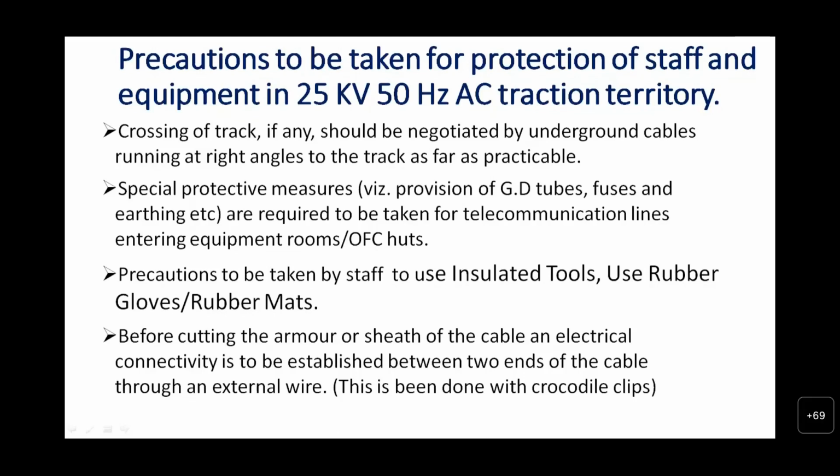Precautions to be taken by staff: use insulated tools, rubber gloves and rubber mats. Before cutting the armor or sheath of the cable, this is very important, an electrical connectivity is to be established between the two ends of the cable through an external wire. This can be done by using crocodile clips in our regular practice.